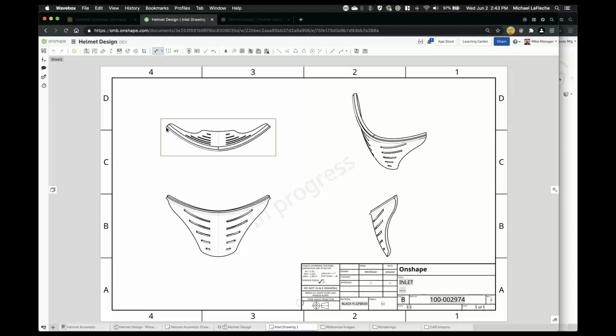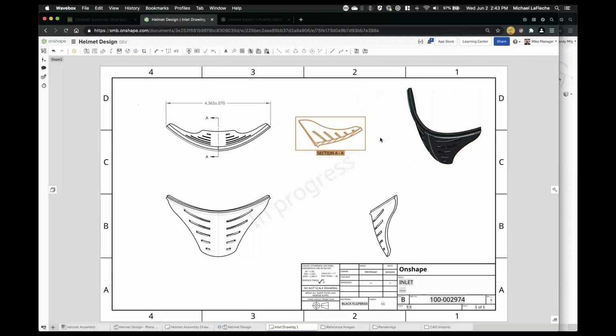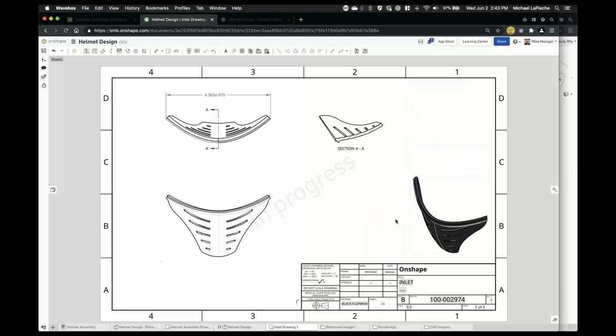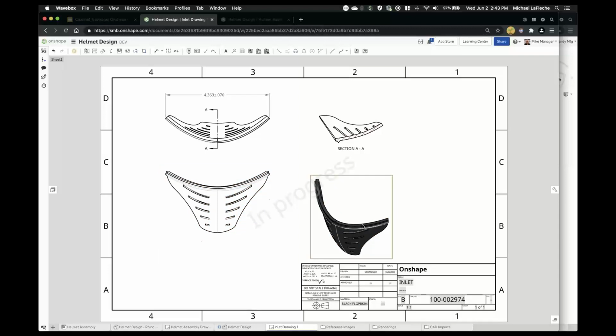And then, of course, I could go in and throw in some inspection dimensions on here, right? So we can pick up on all that information, add tolerances. I'm not going to do a big, long drawings demonstration, but that's pretty much the process that you would expect to see. Section views through various portions of the design are sometimes handy for thin-walled parts to describe the wall thickness, right? So pretty easy to do that. We might not need that view, so I'll get rid of it. Mind you, we're doing this all in a MacBook, all in a web browser, no install required.